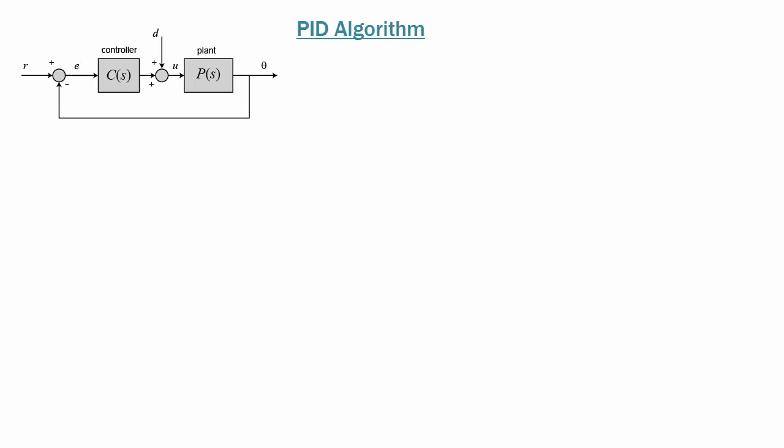So this is how it's normally shown in theory. You have a controller. The output goes to a summer block with an external disturbance, unmeasured or measured, and that becomes input to a process. The output is then measured, fed back to the set point, subtracted from the set point to give an error, which goes back into the controller.